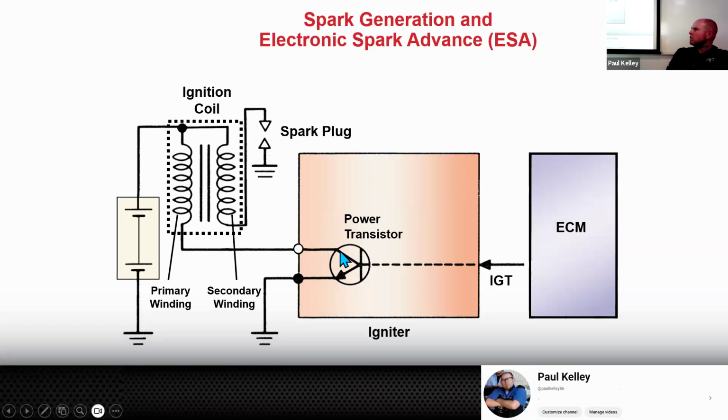And then look, if this transistor is connected, it's giving it ground, right? So right now it's giving it ground. If this gives the correct signal, let's say the signal in this case is 12 volts, it can close this transistor. Or maybe this transistor is normally open, and while it's getting 12 volts, it makes it closed.